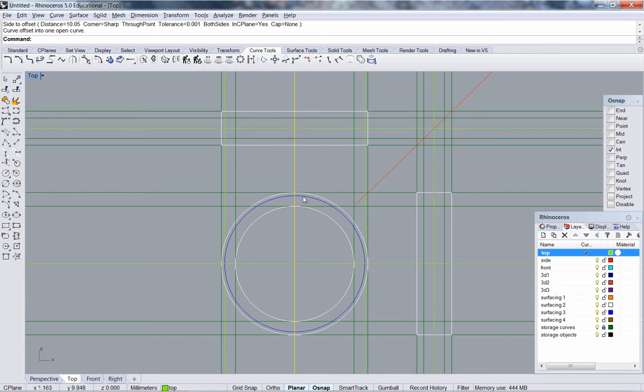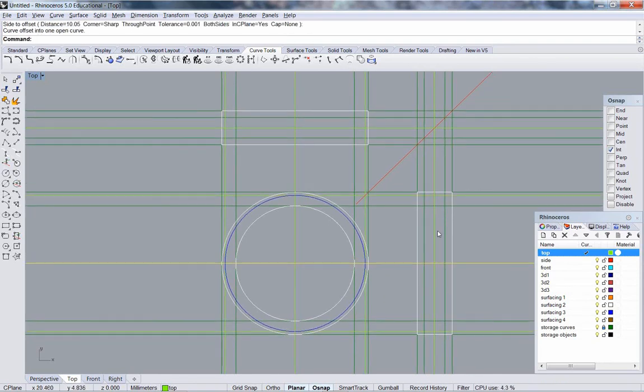It's nothing. Remember, you can only carry corners and edges from view to view. Here I have an edge. As this goes around, you can't see the back of it from the top, so that's an edge, and that gives me my width. Same thing carrying the information over to the side. Okay?